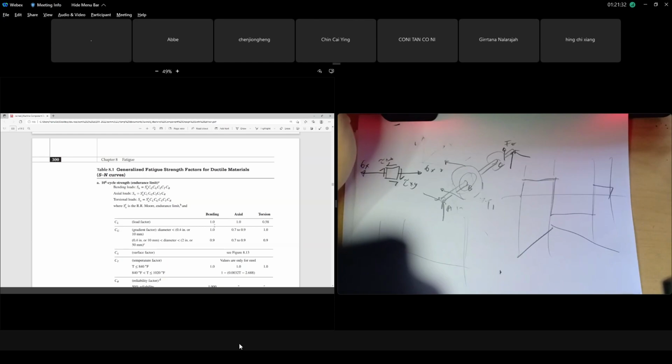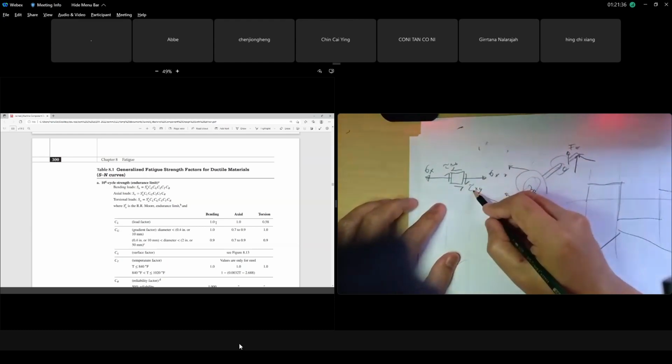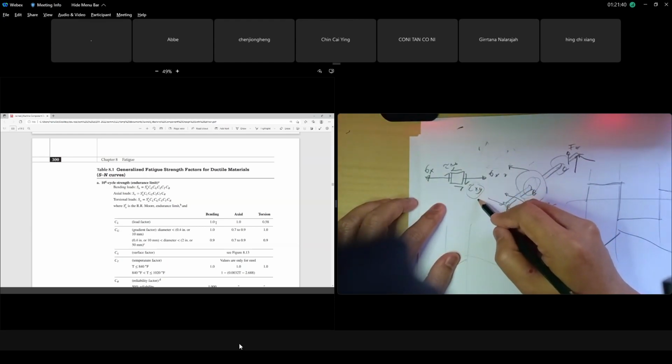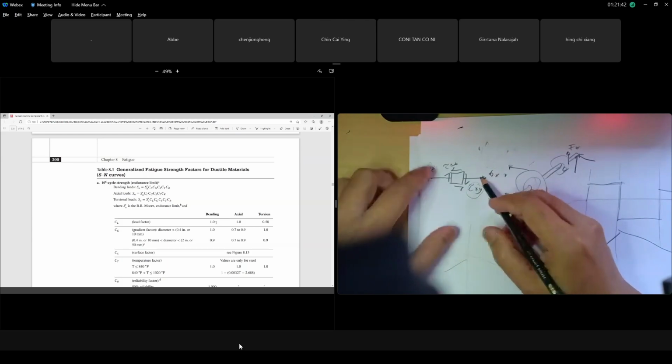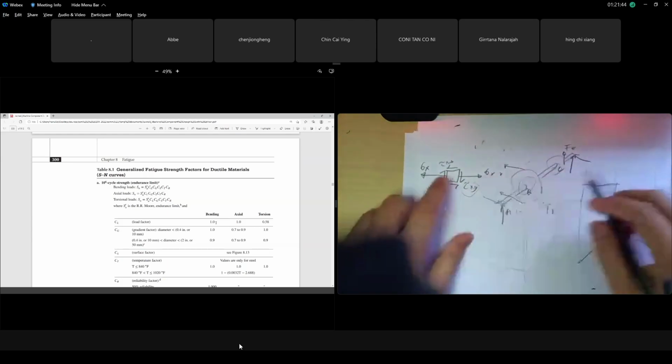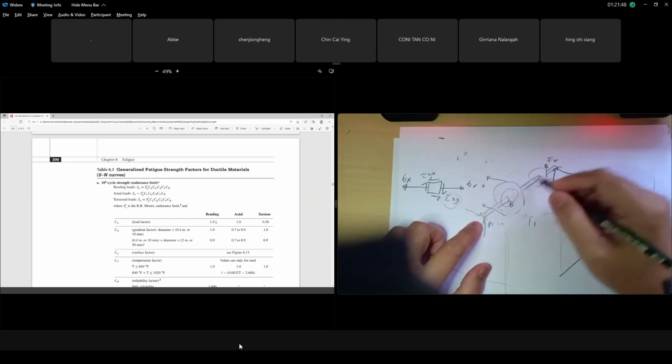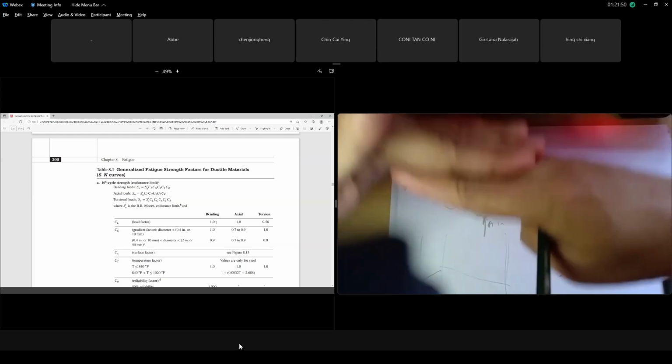Yeah, that's my point. Unless, remember you have torque, SY, right? If you find out tau XY in megapascal, is it greater than sigma X? Normally for a shaft, the critical one is always bending, because on a shaft you mount your pulley, you mount your gear, you are always trying to bend the shaft.